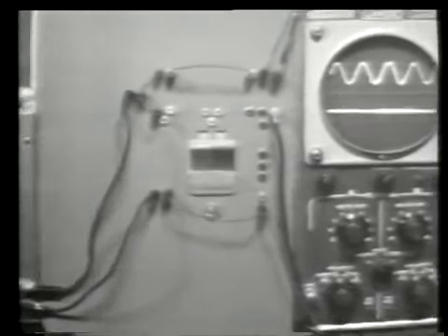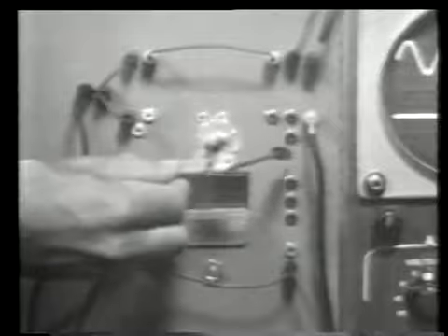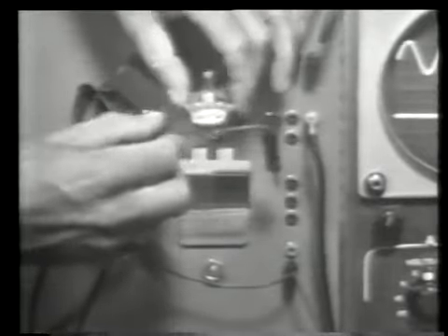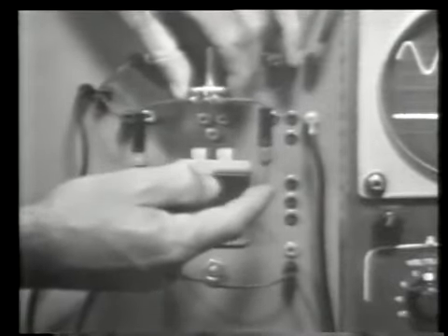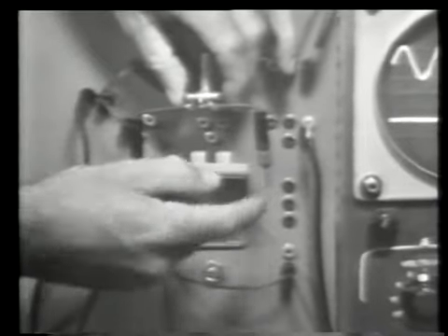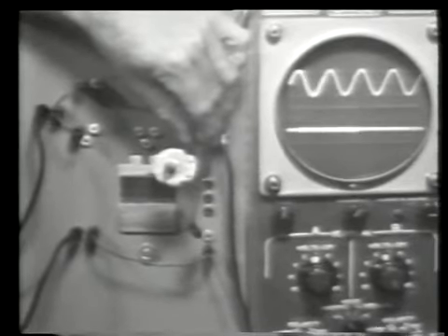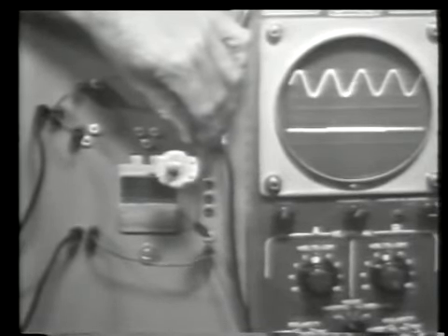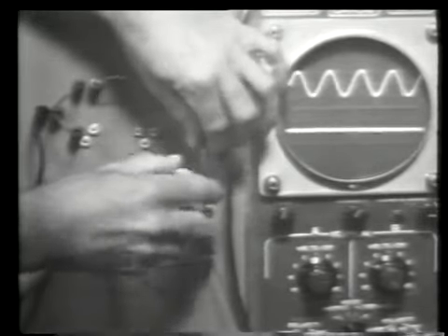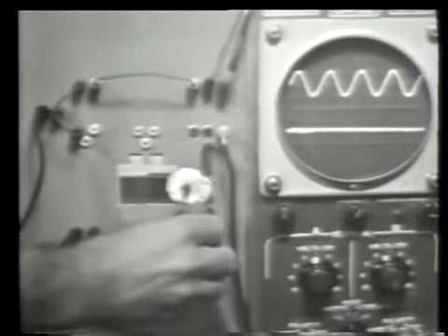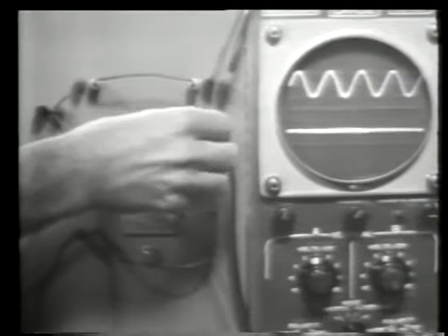To show how a simple voltage divider can provide filtering, we'll use two variable resistors, just like this one. Now you'll note that this is nothing more than a variable resistor that I've connected with a couple of test leads so that I can plug it directly into my trainer for use during the demonstration. Now we'll put one here in the series position and one here in the shunt position to illustrate how the voltage dividing principle will work to affect the output voltage. Well, here, I'll just plug this one in, the shunt position, like that, and there. And we'll put this one in the series position,